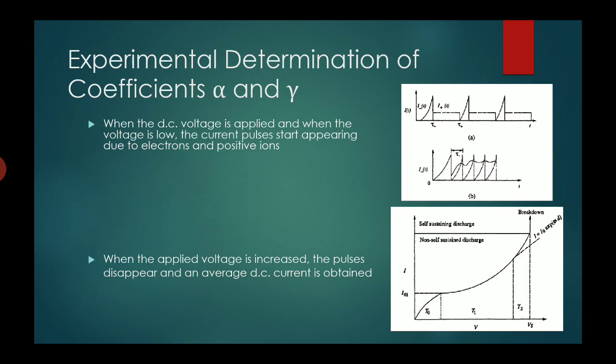We irradiate the cathode inside the chamber with the ultraviolet ray, and the UV radiation produces the initial electrons, that is N naught, which we have discussed previously, by photoelectric emission. So we start our breakdown by injecting UV ray on the cathode, so that the cathode releases N naught amount of electrons.